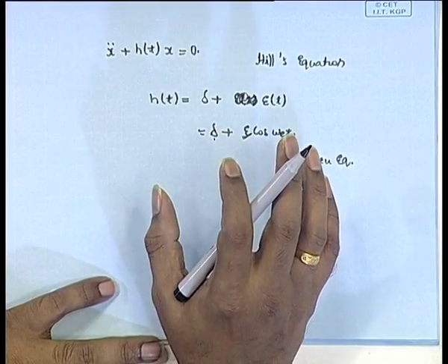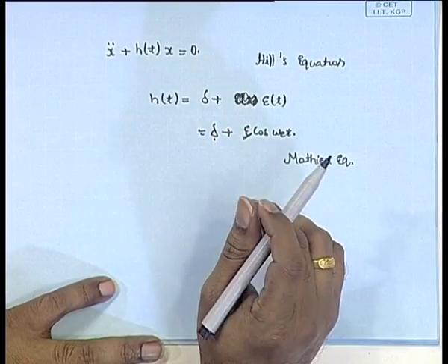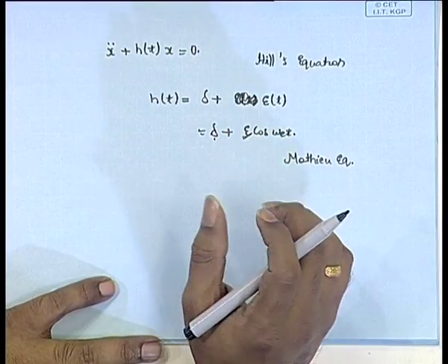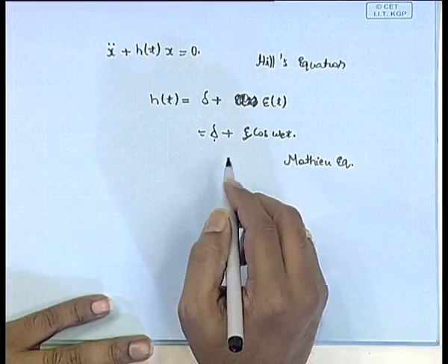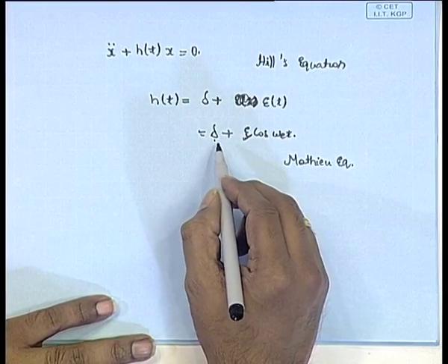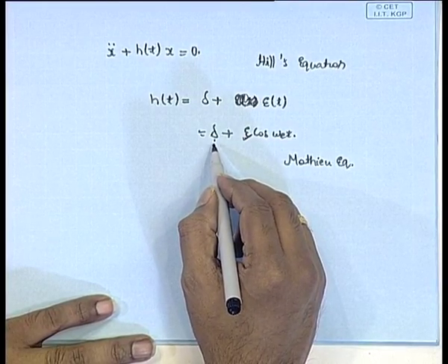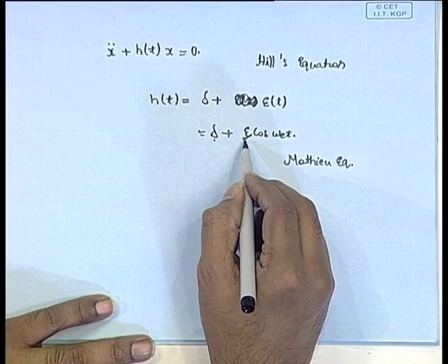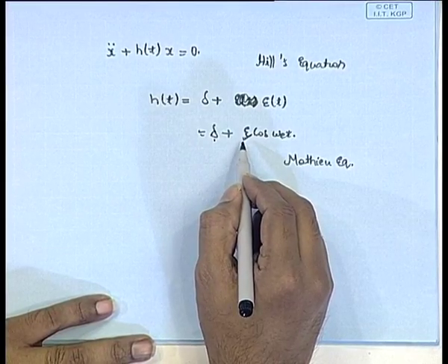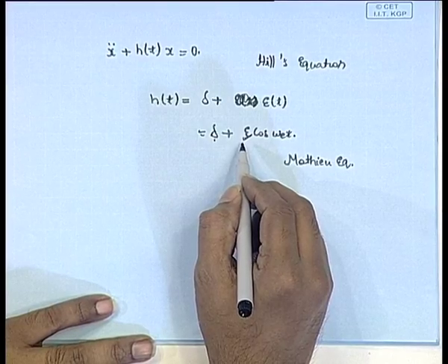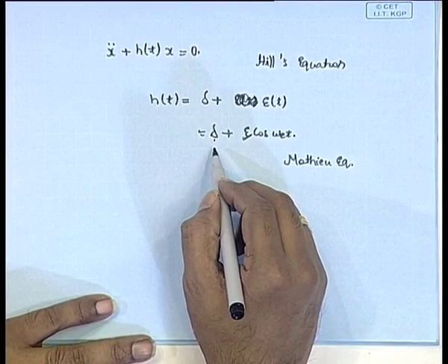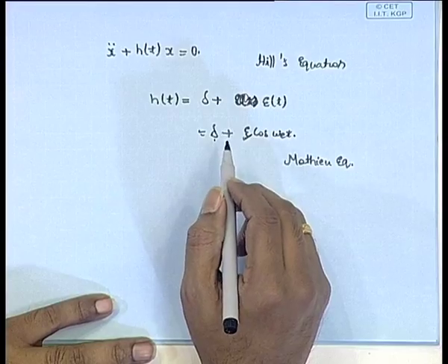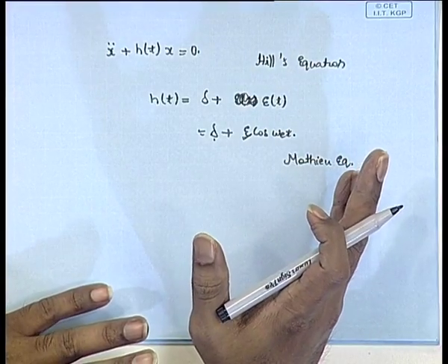So, this is Mathieu's equation applied to ship motion, the differential equation applied to ship motion. In the case of ship motion, the Mathieu equation will have the following constants. Delta will be equal to GM and epsilon will be delta GM. Right from looking at it, delta represents a stable, natural component. GM natural means GM is a property of the ship.